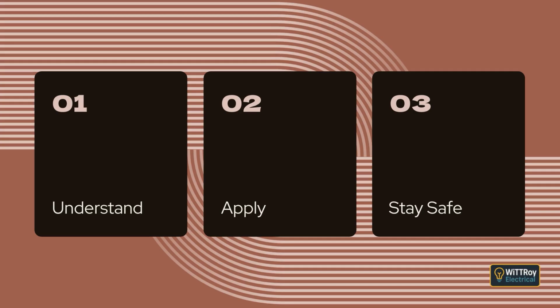Clause 3.3.1 General. This part explains that wiring systems must stay safe and work properly in whatever conditions they face once installed. The shape, design, and construction of the wiring system all contribute to how well it handles these external influences. The installation may also include extra protection or features that help it cope with the environment. The system must be able to protect itself against things like moisture, impact, dust, and other environmental factors. There is also a reminder that the IP classification system, in another standard, is a guide to how well equipment resists entry of water and solid objects.